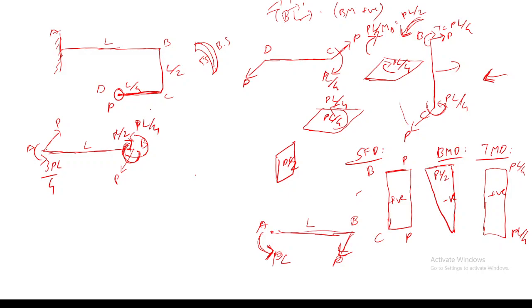Yes, sir. Again, due to this bending moment PL by 4, I will be getting a reaction P into L by 4 in the opposite direction. So these two are opposite bending moment reactions. So the net bending moment reaction will be towards this direction because PL is greater than PL by 4. So when I subtract PL by 4 from PL, you will be getting 3PL by 4. I'm not coming to negative or positive, but I'm just saying it is towards this direction.